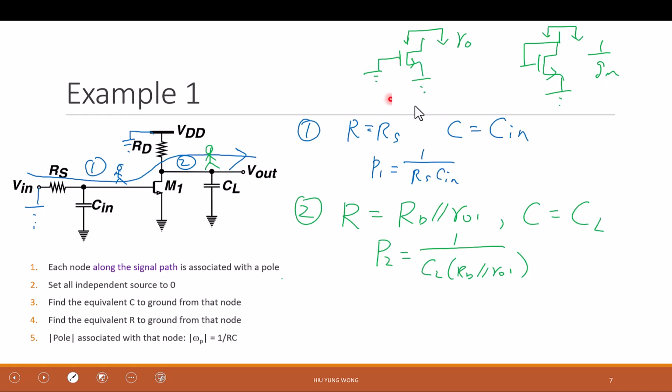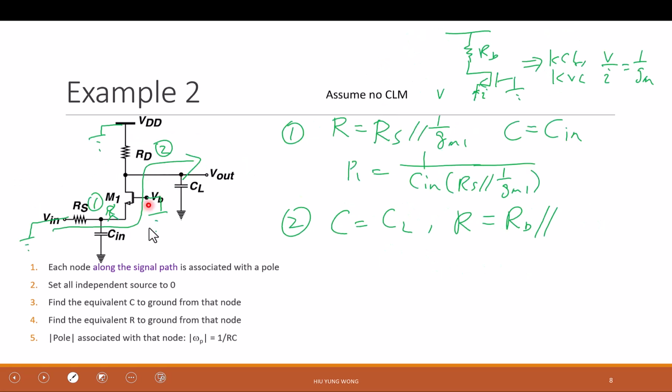As I just discussed, gate and source need to be grounded. Is the gate grounded? Is the source grounded? No, right? Because it's connected through a resistor to the ground. So when you look down, what type of impedance are you seeing? I mean, from this point. Do not tell me it is R0 plus RS, okay? What should that be?